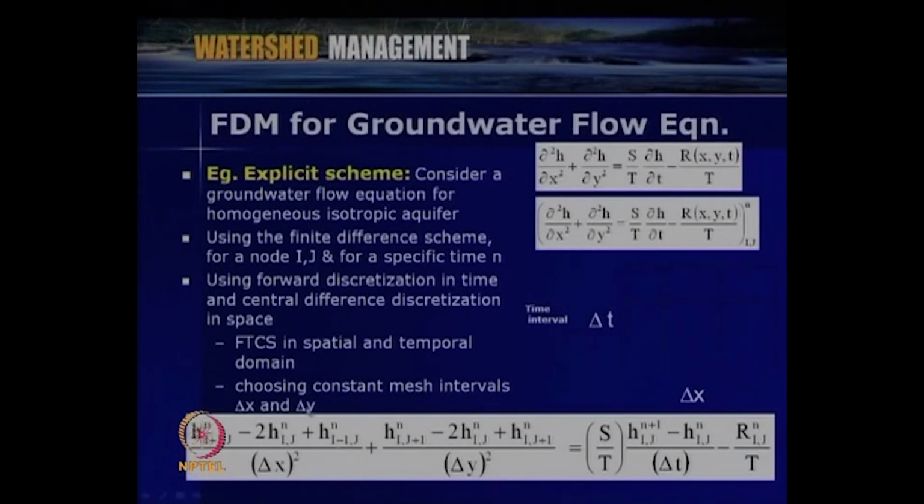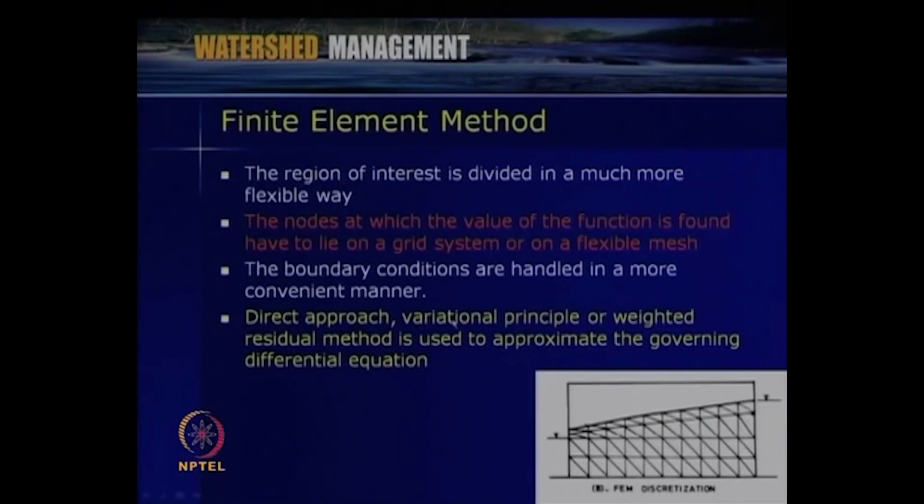These details are available in textbooks like Introduction to Groundwater Modeling using Finite Difference and Finite Element Methods by Wang and Anderson, and Jacob Bear's Groundwater Flow and Dynamics of Porous Media. These books give all these details. Due to lack of time, only one lecture is dedicated to groundwater flow, so I am not going into the details of these methodologies, but the finite difference explicit scheme we can obtain as shown in the slide.